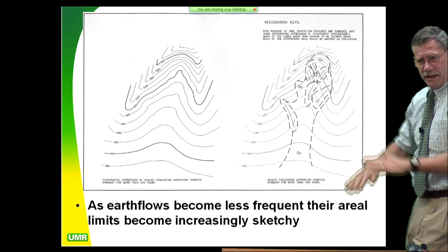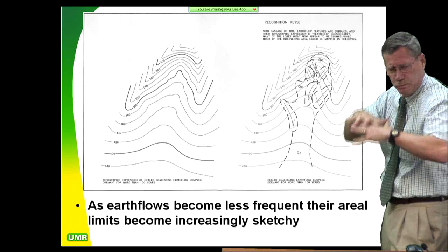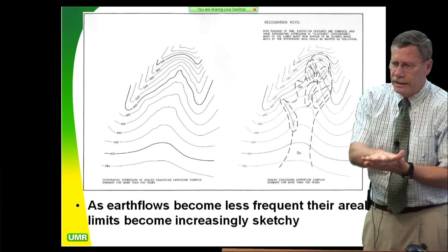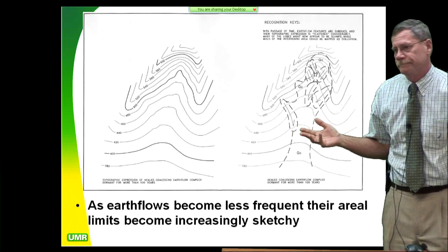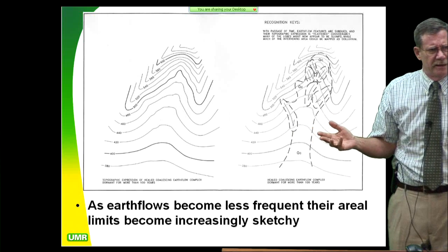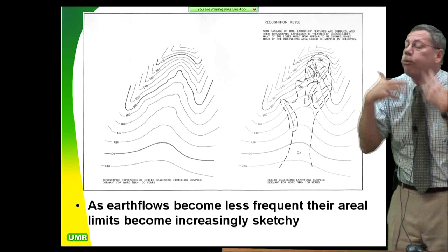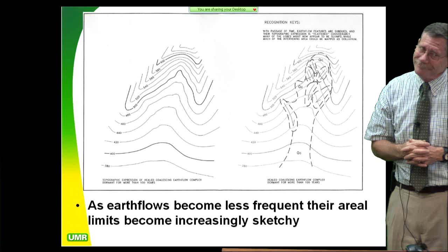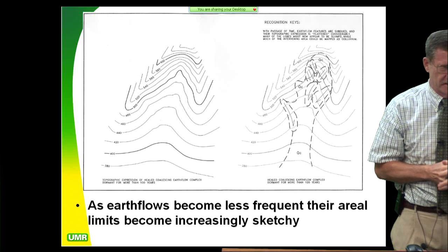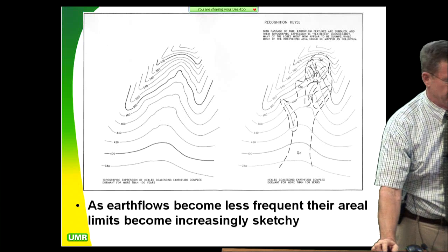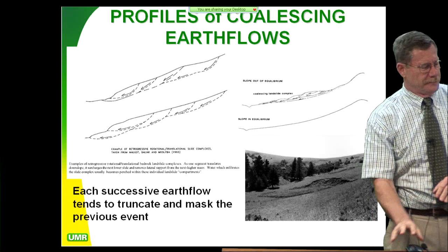But you think about it, you're not going to get a nice slide plane when that all just hiccuped, vomited onto the slope, and just blew out onto the grass. You're not going to get a well-developed slide plane. But is it slide debris or is it colluvium? Well, you have to ask yourself, how did it get there? By gravimetric processes or all at once? Yeah, I think it's pretty self-evident. It all got there by the vomit deposit all at once. That's slide debris. Okay. Hope I'm not ruining your dinner.